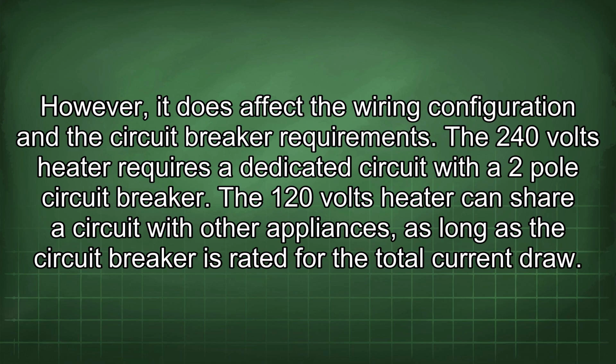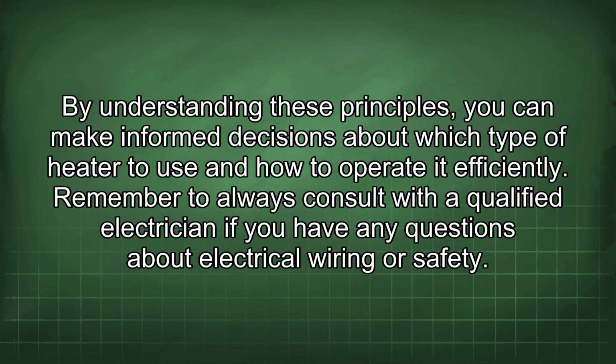The 240 volts heater requires a dedicated circuit with a 2-pole circuit breaker. The 120 volts heater can share a circuit with other appliances, as long as the circuit breaker is rated for the total current draw. By understanding these principles, you can make informed decisions about which type of heater to use and how to operate it efficiently. Remember to always consult with a qualified electrician if you have any questions about electrical wiring or safety.